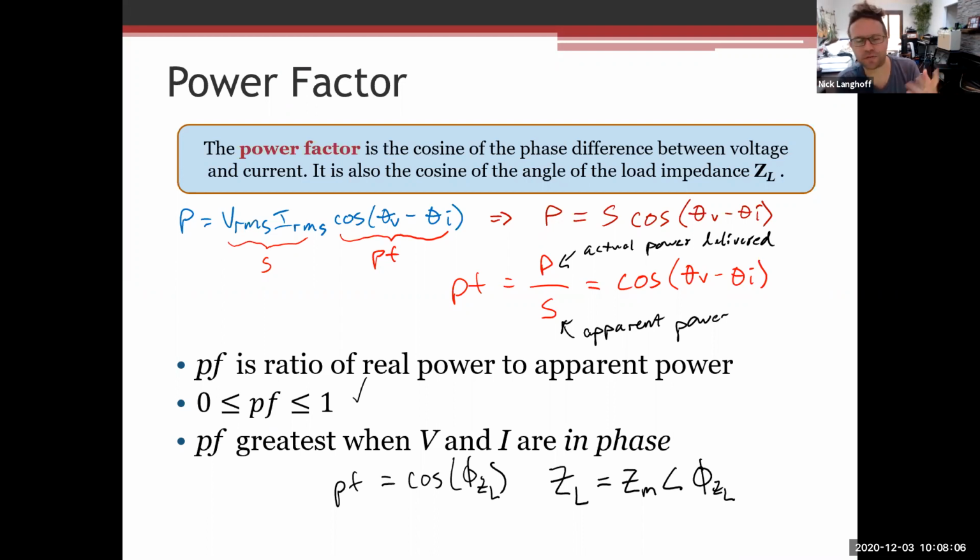The L part of the inductor doesn't really do anything, but the resistance of the windings, let's say around 10 ohms, the DC current through that is always going to be losing energy. So in terms of the energy lost, you might actually have a lower loss from the effective DC current IRMS than you would from a